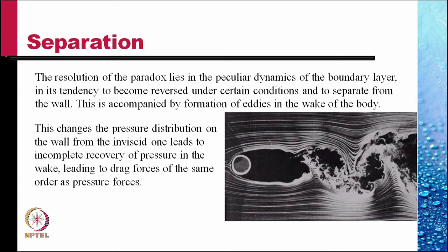This changes the pressure distribution on the wall from the inviscid one and leads to incomplete recovery of pressure in the wake, leading to drag forces of the same order as pressure forces.